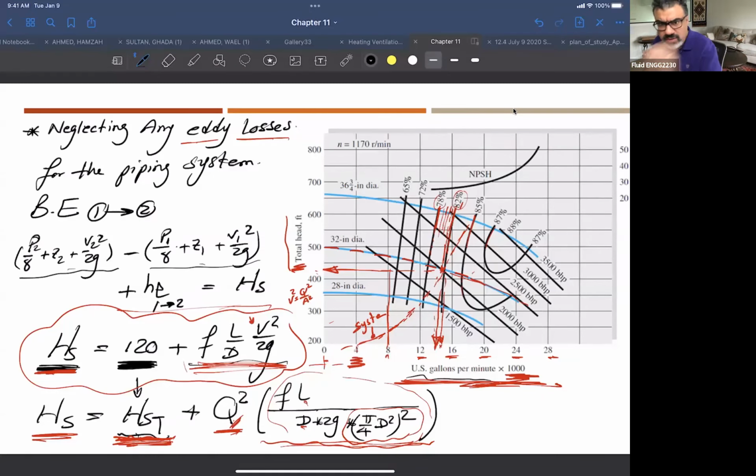So the flow rate has to be constant, and that's why the performance curve of the positive displacement pump is a vertical line on the HQ curve, right? The same flow rate at a certain RPM, of course. You only have leakage when you have very high pressure, if you remember. So there is no which one is better to use, right?